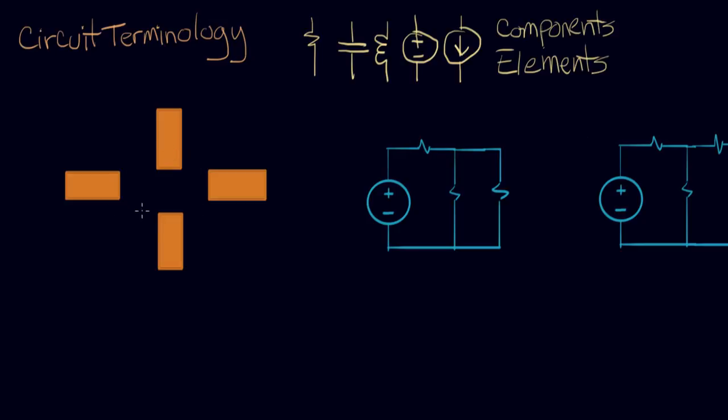Here's some circuit components that are laying out on the tabletop, and we're going to connect those up with a wire. So for example, I could connect this one to this one with this yellow ideal wire, and an ideal wire has zero resistance and it's perfect everywhere, and this forms a junction between these two components, and that is called a node. Node is the word for junction, they mean the same thing. If I connect up these two other components, I still have one node because I have one junction that's the same voltage everywhere. So that's what a node is.